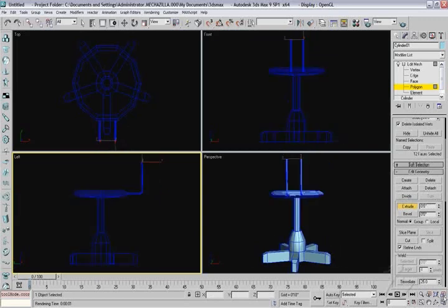And we'll hit our zoom extents all button. As you can see now, we've got 2 decent pipes coming off the back, and they should be coming straight up and down. Remember, if they're crooked or whatever, you can use your move tool, grab those polygons, and move them around. In this case, I'll undo to reselect them, and I can kick them back at an angle if I want, or whatever have you.